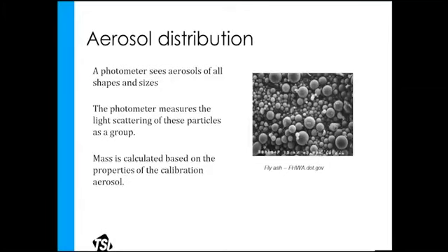So people come and ask, well, what is the cal factor for this? And I've been doing research, I've been pulling lists, I've been finding some for oil mist, I found some at 0.7, for forest fire smoke, I found some at 0.65. So the aerosol's going to be different. Your aerosol's going to be different than mine. Even if I had a list, it may not apply to what yours are. But that's how this instrument will get a better number, is if it's calibrated.